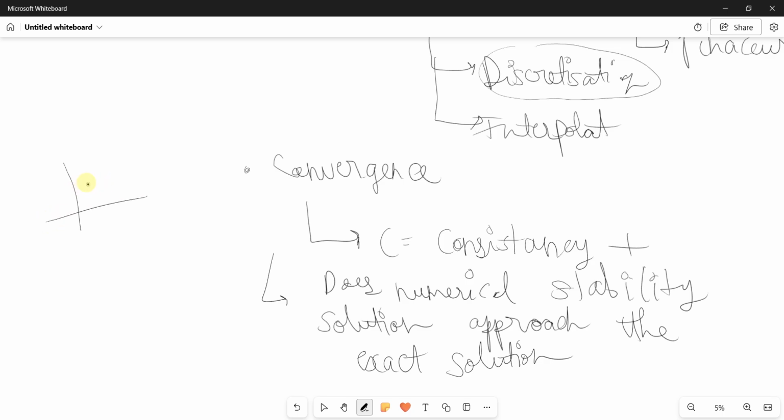So usually in your answer in Fluent, or something, its solution with respect to time steps, you will see that the value converges like this. And if it is not, it just goes like this, just diverges out of the plane, right? So that is something that we don't want.